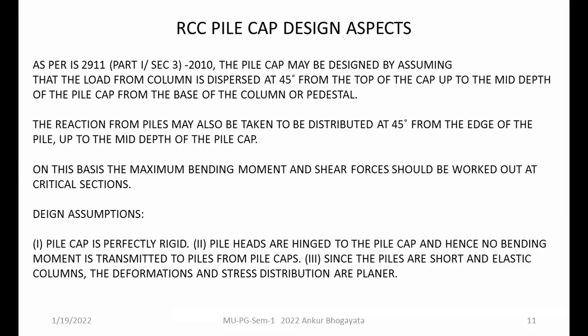But as far as the connection between the piles and the pile cap is concerned, we assume that the primary function of a pile cap is to hold the piles in position. That's it, nothing beyond that. Otherwise, what happens is you have to unnecessarily design the piles themselves for the bending itself. It becomes like a rigid cantilever in that case, that means fixed at one end and free at the other end.